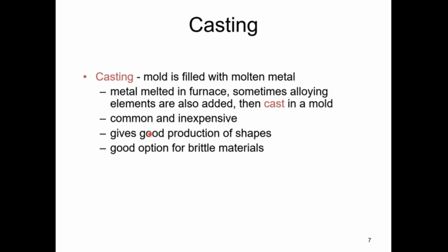Casting is a fabrication process whereby a totally molten metal is put into a mold cavity having the desired shape. Once the molten metal solidifies, the metal will follow the shape of the mold with a little bit of shrinkage in size. A number of different casting techniques are commonly employed, including sand casting, die casting, investment casting, and continuous casting.